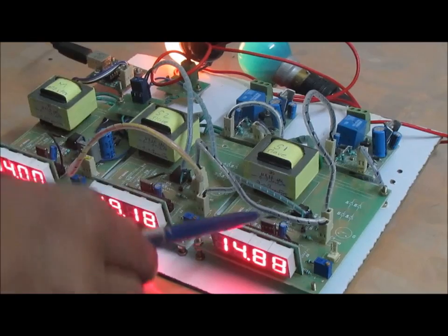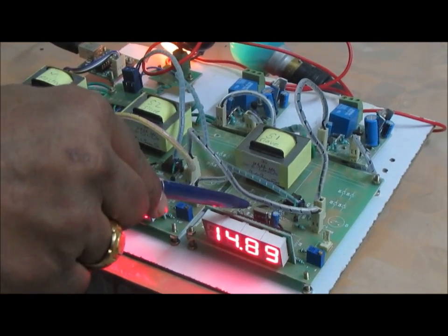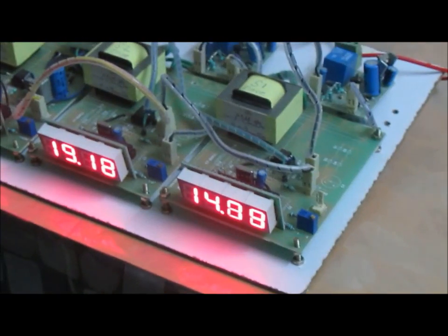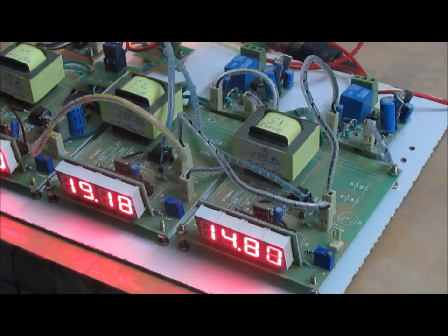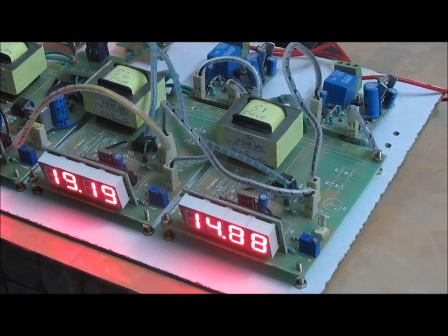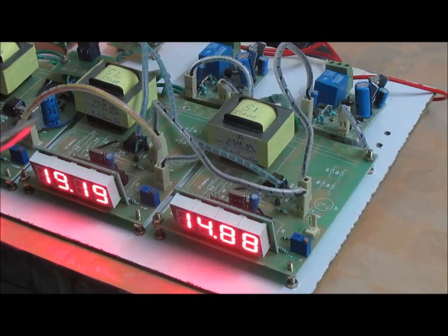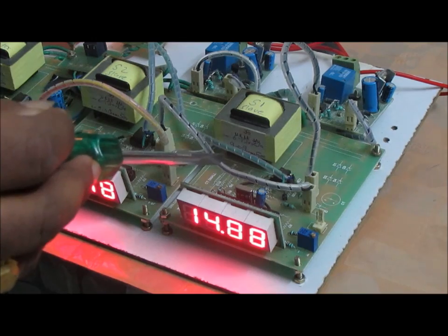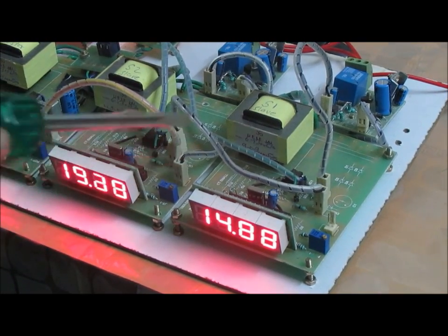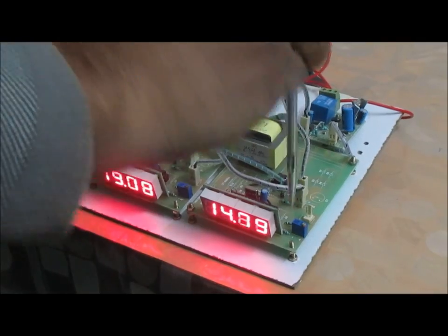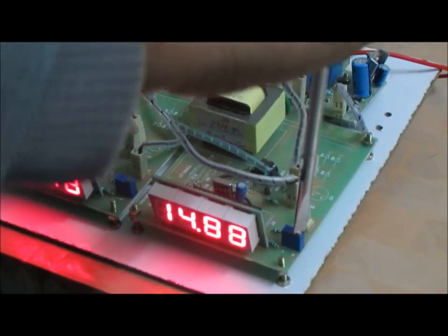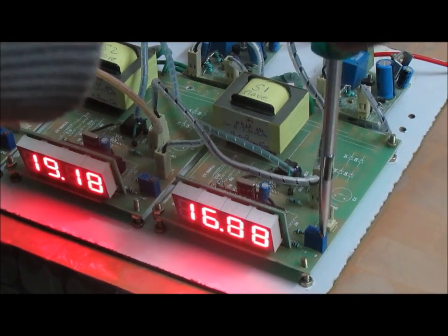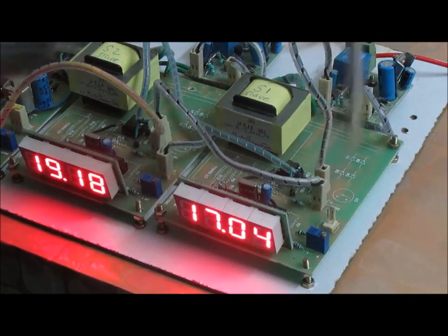Now this one is a microcontroller unit, which is measuring this value from this port. This port can be varied using a screwdriver. So right now, if I vary it using a screwdriver, then its value will vary from 0 to 255. Now this value is going to this microcontroller, and this microcontroller is displaying this value on this seven-segment display. Now I will show. Now I am increasing this value. Now I increase to 16 and 17 here.